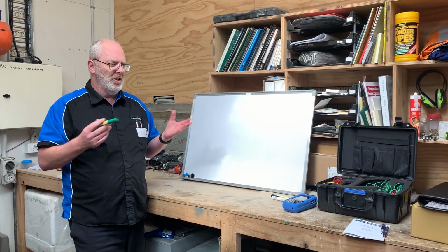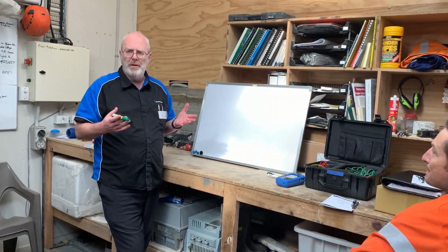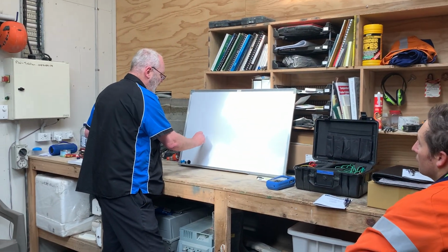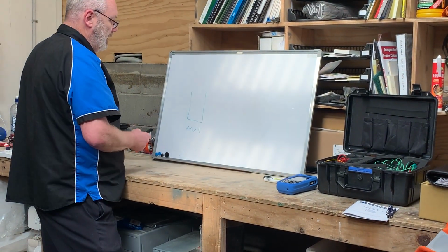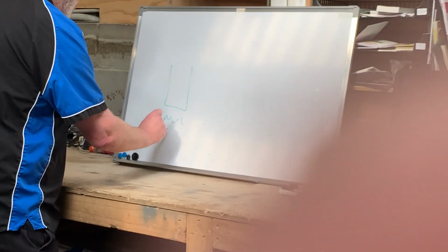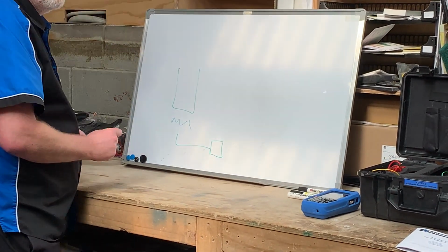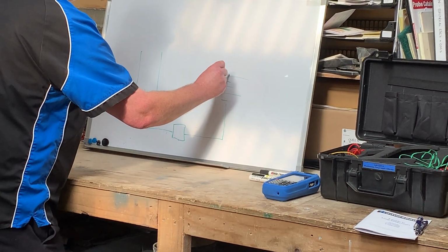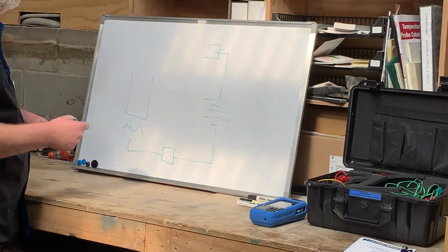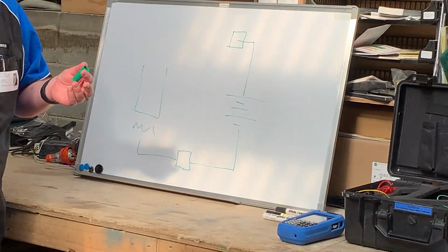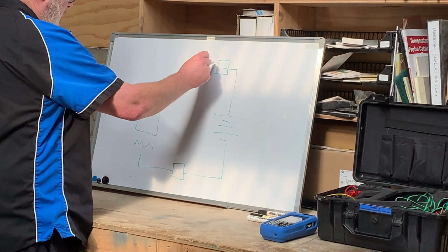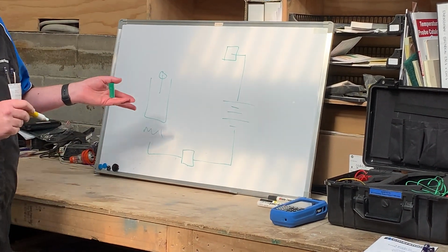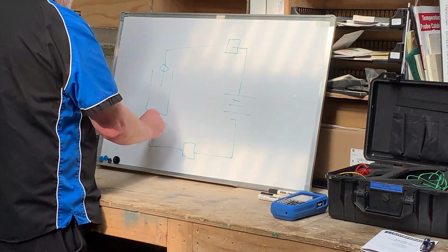Questions about things you know, and forgive me if they're already obvious. So if I draw a basic 4 to 20 loop, and I realise you're all over this like a rash, but here's a gas burner, here's a vessel we're heating, we're controlling that gas burner with an electronic valve, and that's going through a power supply, which will be a battery in this case, through either a PLC or whatever controller you're planning to use. Then you've got a thermocouple or whatever temperature sensing device you have in the vessel, feeding into there and feeding back to here.